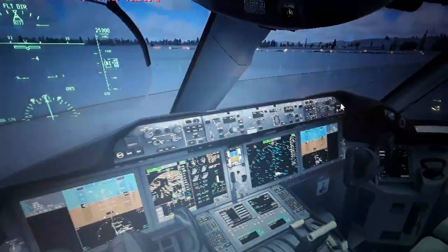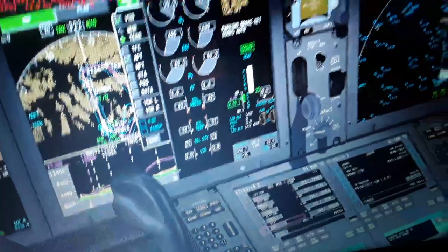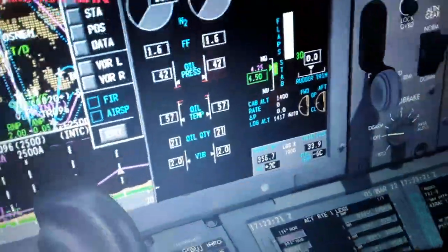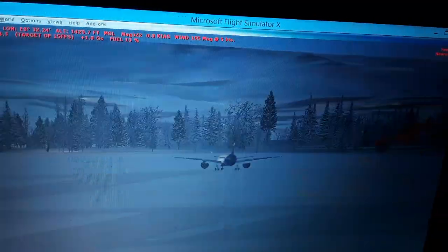You will see the indications also. So we have the FADEC over here. The FADEC are the full authority digital electronic control computers, one installed per engine gearbox, dual channel redundancy. If one channel fails, the other takes over. Controls modules displays all the engine data, showing the engine case control system display.